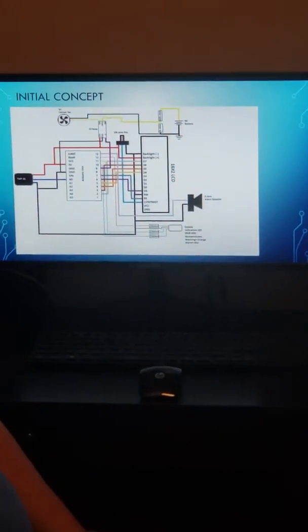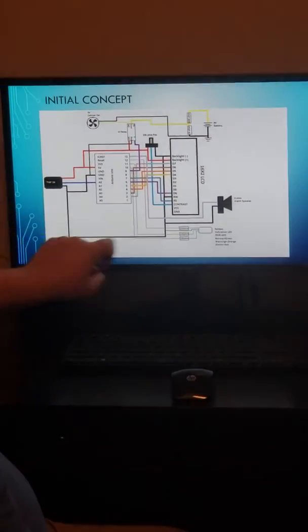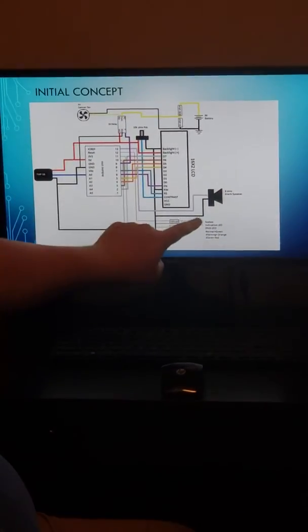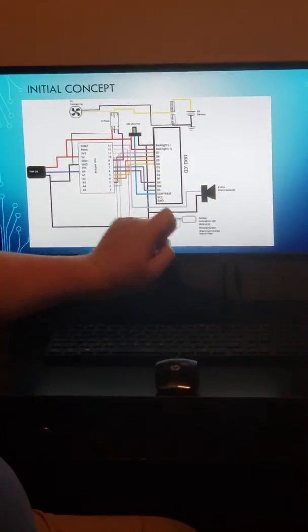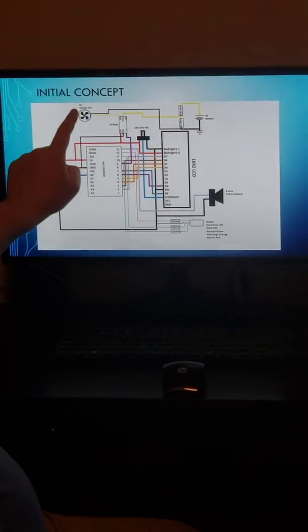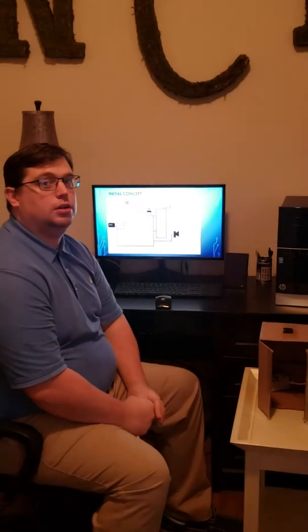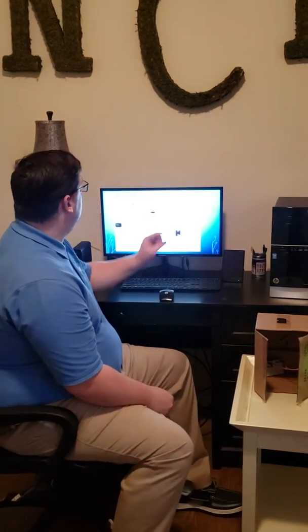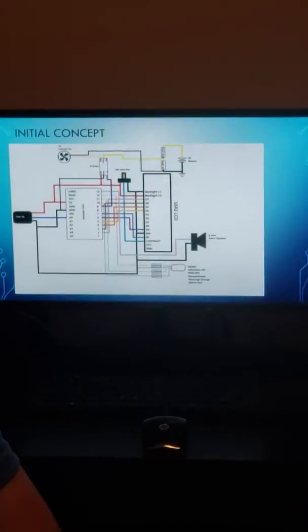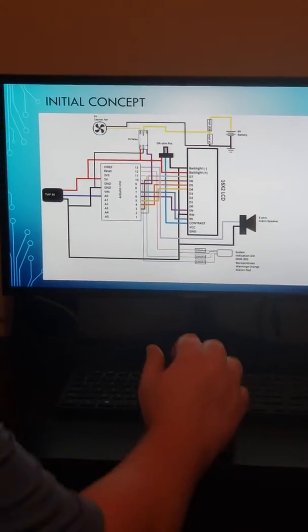This is my initial conceptual design, showing the temperature sensor, the indicator, the audible alarm, an adjustment for the display of the temperature, the panel display, and a fan. I also used a relay instead of directly hardwiring the fan. So if need be, the fan can be upscaled to a higher voltage or higher current drawing fan to cool the cabinet faster and more efficiently.